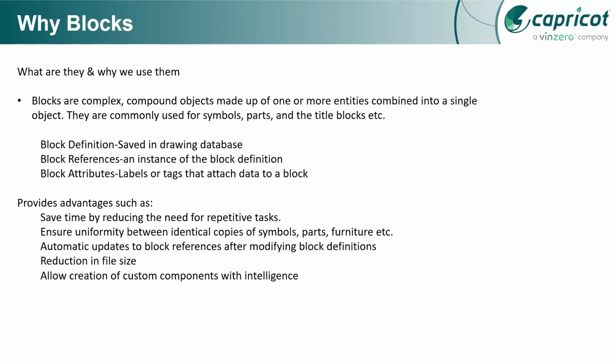And why should we utilize blocks? They have multiple advantages. The first one is that a block is always stored in your drawing database as just one element. The second is that you get instances of block definitions. One block is different from the other. Let's talk about a chair, right? There are multiple varieties of chairs. You want to segregate different kinds of chairs, for use with a study table or with a dining table, right? So they are instances of block definitions.